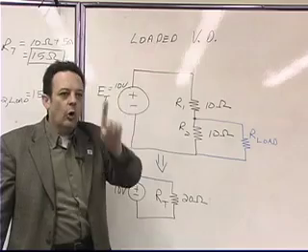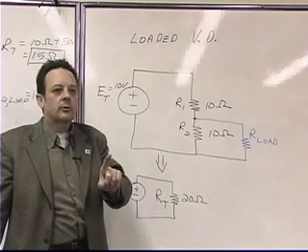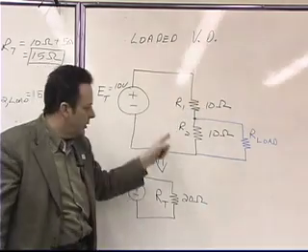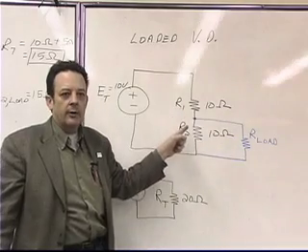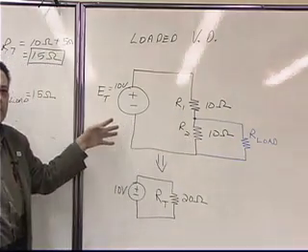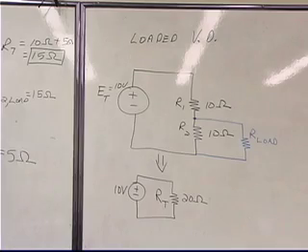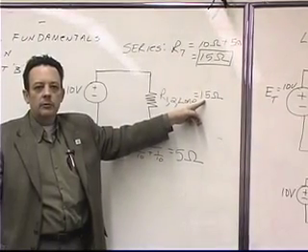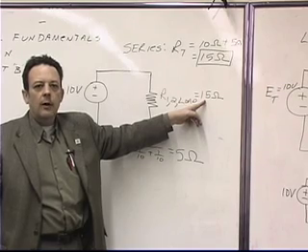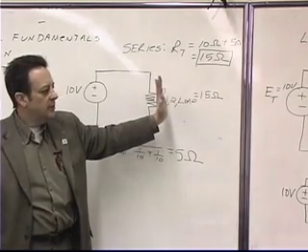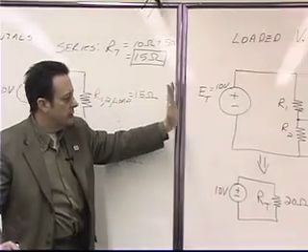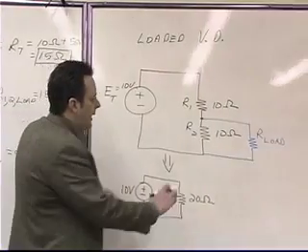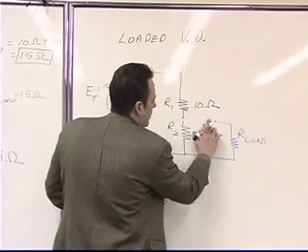What is the total resistance of our loaded voltage divider? And let's scan back over here. 15 ohms. Okay? Now, watch this. Let's scan back over to this circuit over here, and let's remove the load.